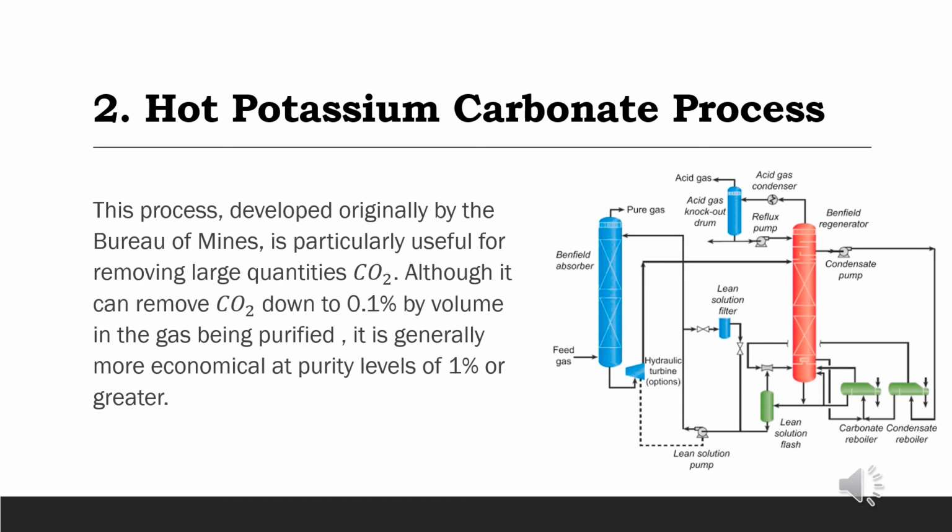By absorbing CO2 under pressure in hot solution close to its boiling point and generating it at the same temperature but at near atmospheric pressure, steam consumption is reduced and heat exchangers are eliminated. Process improvements have been obtained through the use of catalytic additives and promoters to the solution, such as in the Giammarco-Vetrocoke and the Catacarb processes.